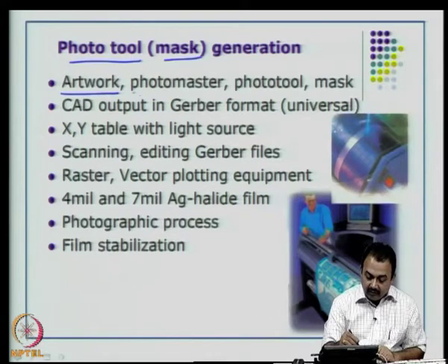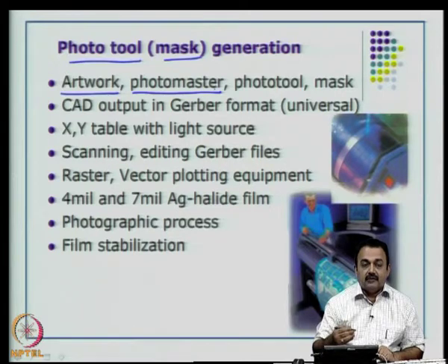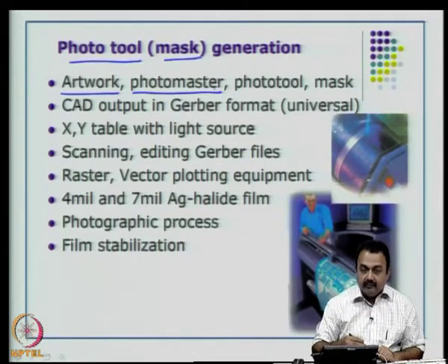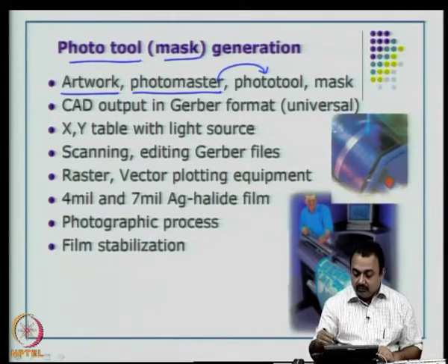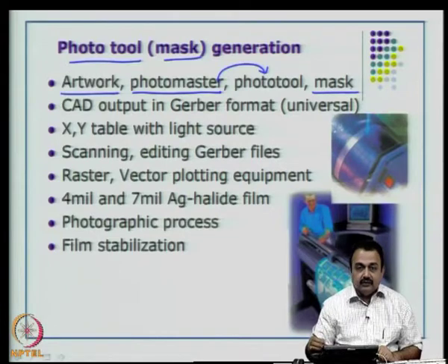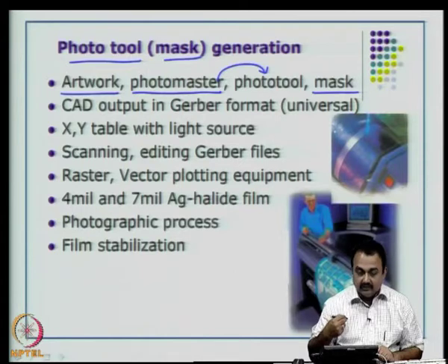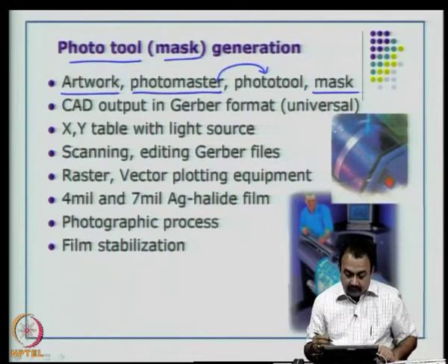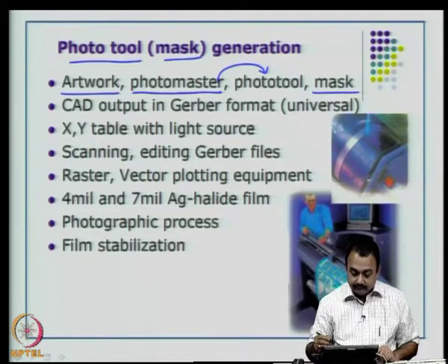So, you can call it a photo master, that is your photo tool can be a photo master if you want to preserve it for a long time, and if you can use some thick polyolefin layers to generate your mask, and from the photo master actually you can create a photo tool. The photo tool or the mask is basically used for actual handling and fabricating the PCBs. It is used in the workshop floor of a printed wiring board industry. So, it is very convenient to use the term mask or a photo tool.